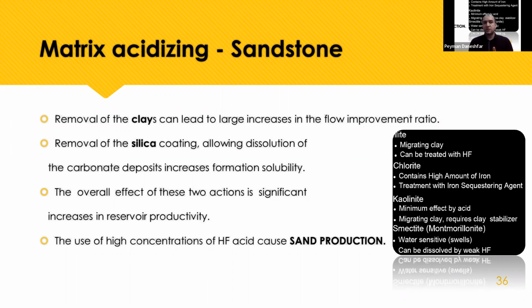Removal of silica coating allows the solution of the carbonate deposit, increasing the formation solubility, because the acid removes some cementing bond that contains the limestone, and we can increase our permeability. The overall effect of these two actions is a significant increase in reservoir productivity, and the use of high concentration of HF acid causes sand production.